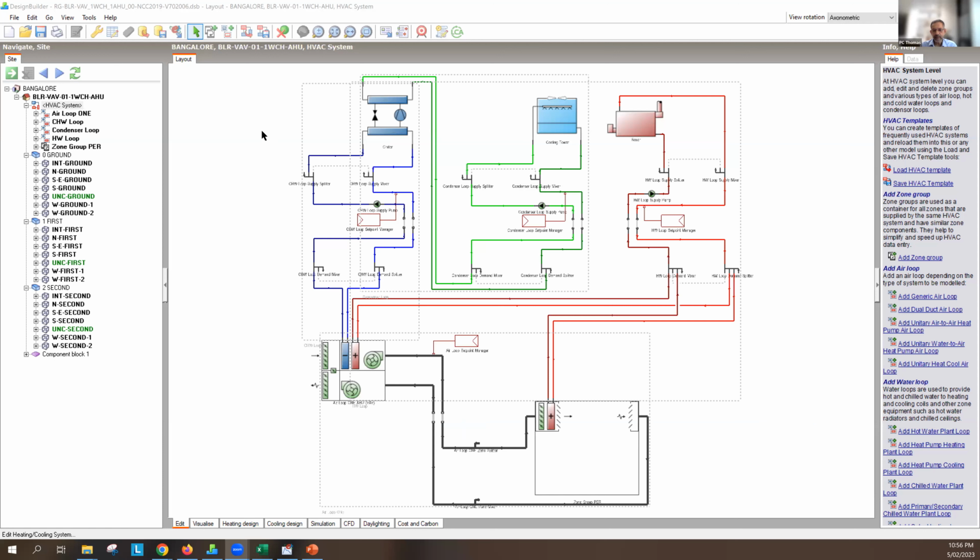So last time we went through how to model a VRF system, or what we call a direct expansion system. This time we look a little bit at centralized systems. When I say centralized, I'm talking about chilled water type systems, whether the chiller is air cooled or water cooled. These systems have one chiller object, and that chiller object will produce chilled water.